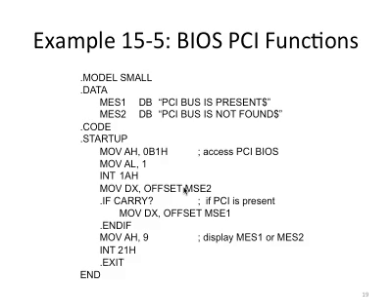This is an example where we use one of the BIOS PCI functions. By moving 0B1h to AH, we're going to use one of the functions of this PCI command presented by the BIOS. This int 1A is to call the BIOS to execute these PCI-related functions, and this B1 is the particular function we will need to use.